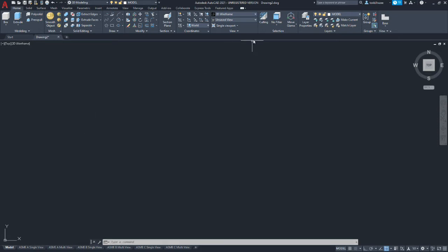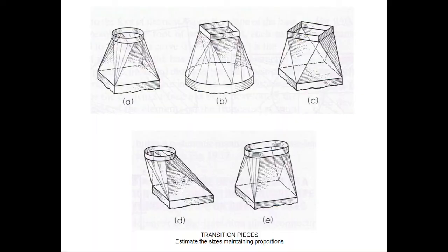We're in world coordinate system. We're going to switch to the top view. And this last one, what we're doing is an oval. So we're going to just go ahead and I'm going to make that 8 inches wide, and we'll figure something out for the base. Same thing, we need to do a loft transition with having these flat triangular or blunt cone looking sections.